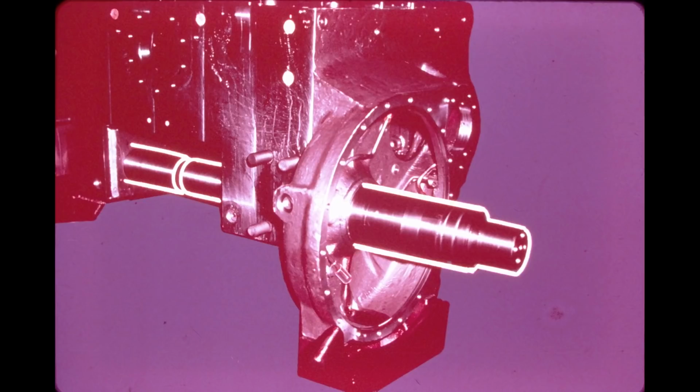The TD9B, TD25B, and TD25C have a pivot shaft pressed into the main case and extending through the center of the sprocket. Notice that the 25B and C, as shown here, actually have two pivot shafts, one for each track frame. The 9B has a one-piece shaft.